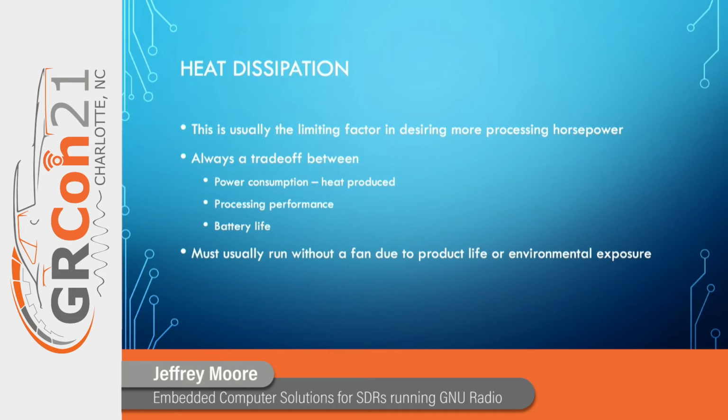And most of these products that you build that are embedded have to run without a fan. They don't want a fan because of environmental applications where you can't be exposed to liquids or some kind of environmental situation, and a fan is not compatible with that, or they don't want the limited lifetime and failures that fans introduce, because it's moving parts. They will not last forever. So almost everything has to run without a fan, which means you've got to get rid of the heat.